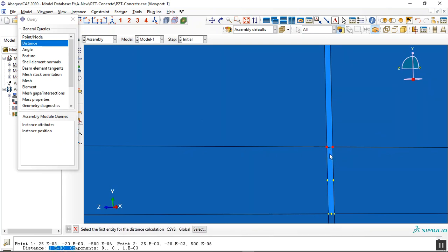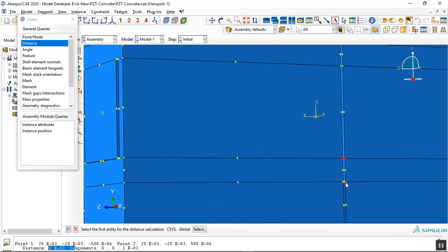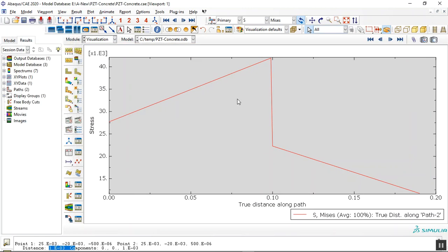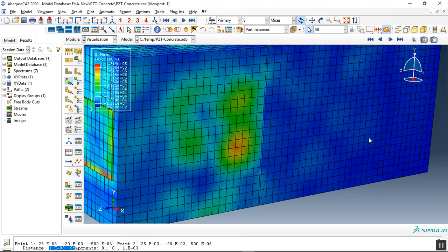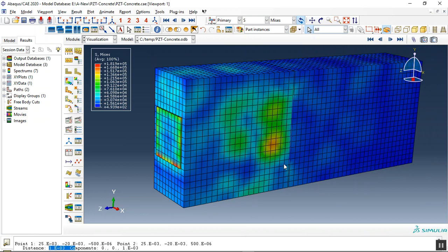This is the length of the crack, sorry, and this is the distance of the side view from the piezoelectric, 99 millimeter. And what is this? By this effect of the piezoelectric, we can find the damage. Where is it and what is the length? We can also use piezoelectric on the side of the concrete here to find the elevation of the crack. You know, we can use that also.